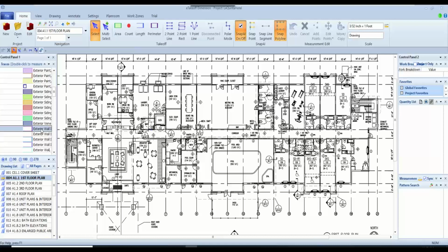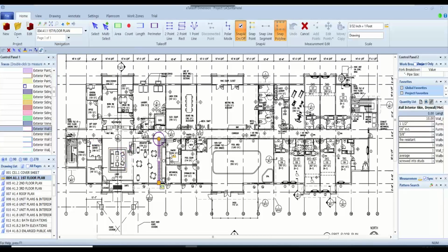And if I double click on my exterior wall, and as I clicked right there, you can see that it picked up a polyline all the way back to the left end side of that building. Now, if I go on here, it's going to struggle a little bit trying to match up the rest of that polyline, which tells me that this really wasn't drawn as a continuous line around there, but that's okay. So I'm going to click on that. We're going to accept that one.